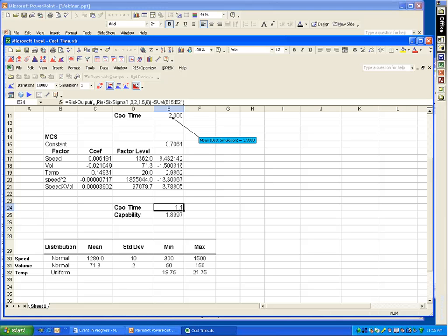And if you know the structure of that distribution, if you know it's normal or whatever the distribution is, you can then translate that area under the curve outside the upper and lower spec limit and convert it to parts per million outside the spec limit. Is that an adequate answer?